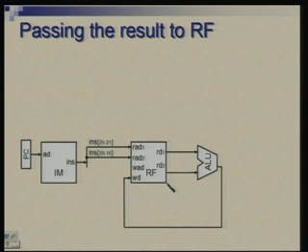port. So, now when we are writing, we also need to arrange for the address where it has to be written. So, we need to look at another field from here and make sure that the address is also delivered correctly to the register file. So, bit number 11 to 15 are the destination address. Okay. And that connects to the third address input. So, now with this the cycle is complete.